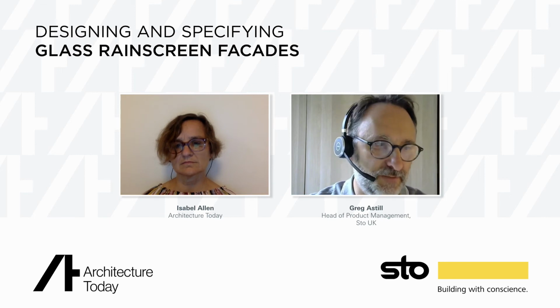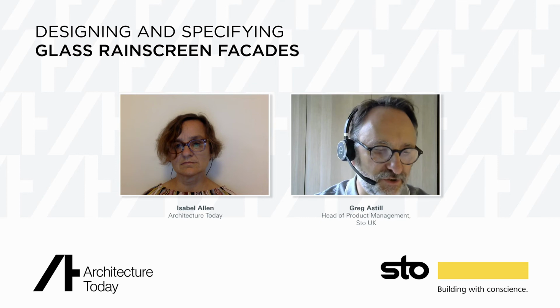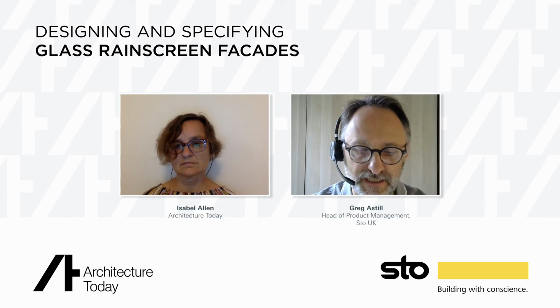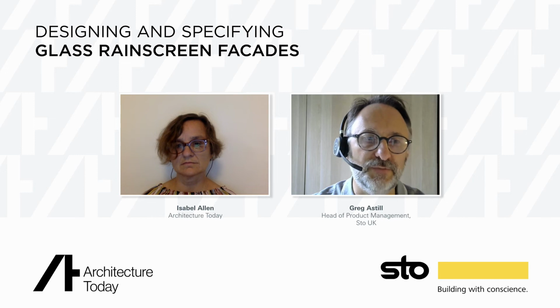Whilst this type of system, any open jointed system, is not watertight and it's not airtight, it's got a lot of open gaps around it, it does contribute to resisting the passage of rainwater onto the inner surface. So your water tightness and air tightness is provided by the substrate, which typically today would be a sheathing board of some kind. That's mostly what we come up against. It's a sheathing board on the steel frame. So that part of the structure would need to perform in that respect.